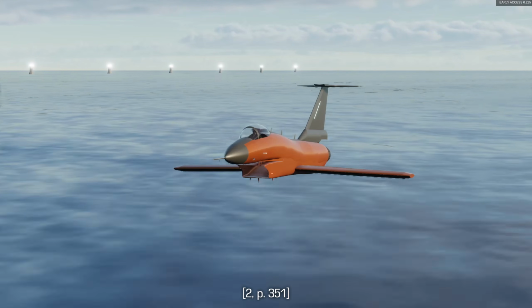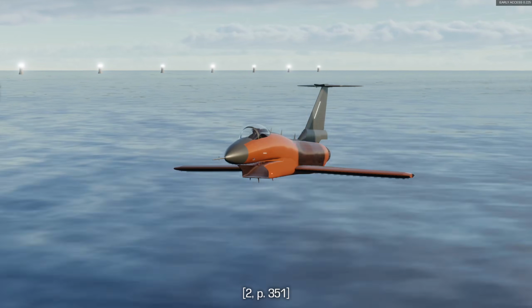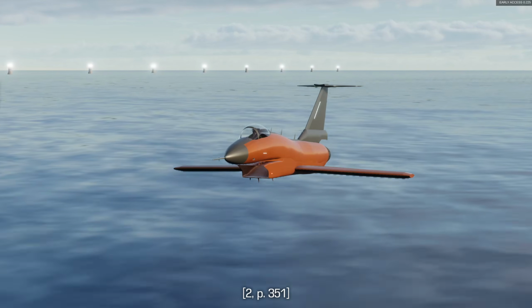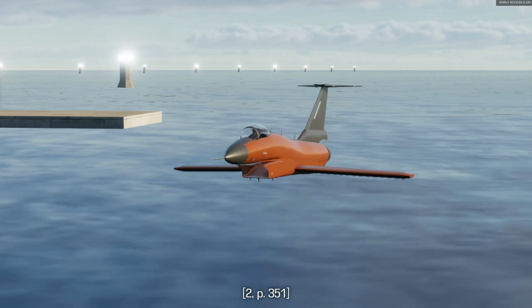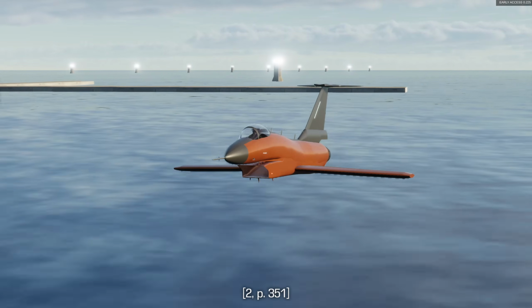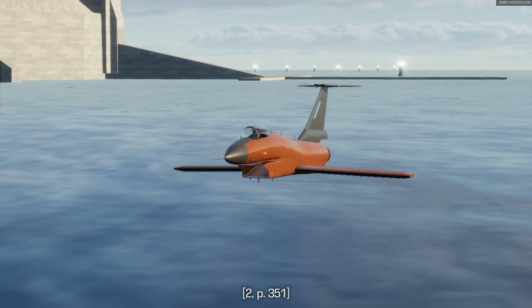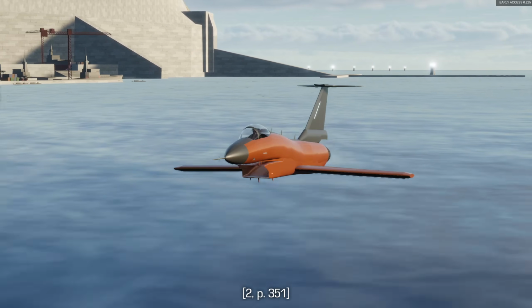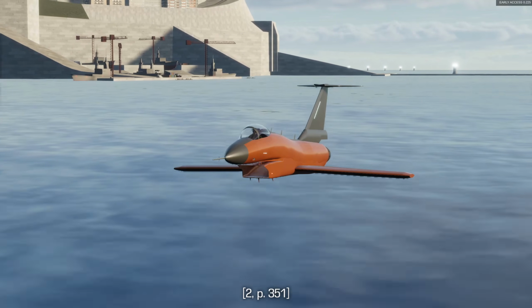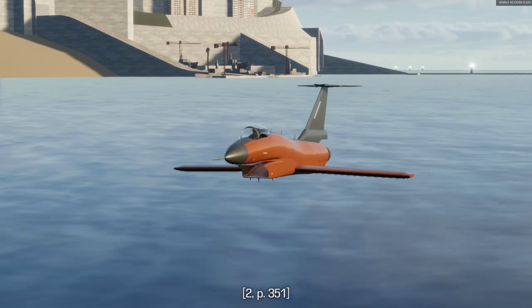The two-dimensional component of ground effect, which pertains to airfoils instead of finite wings, actually sees the airfoil lift decrease due to the increased pressure on the upper surface until getting fairly close to the ground, at which point it will begin to increase slightly due to a pressure increase on both the upper and lower surfaces, with the lower surface seeing a larger increase.